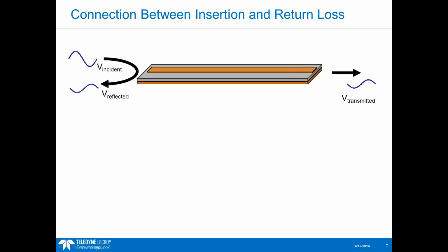Yeah, so on the Spark, we can measure S parameters and show kind of all the things I talked about today. But there's also a live TDR mode, which will show just the live TDR waveforms and TDT waveforms. That's really nice for debug because you can see the results changing live on the display. For example, if you want to twist around a cable or jiggle a connector, you're able to see if that has a big impact on the TDR results. Okay, all right, so CJ, hopefully that helps. If not, let me know.